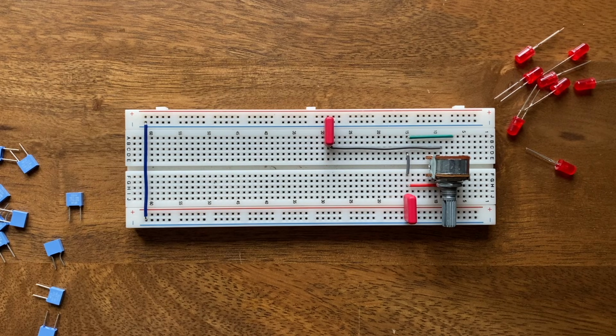Since they're passive, they, by definition, can't apply any kind of amplification. So as we close the filter, the sound gets more and more quiet. Second, and very much related to that, a passive filter can't produce any resonance, because resonance is created by amplifying some select few frequencies. And finally, our design only allows for the cutoff point to be controlled manually.